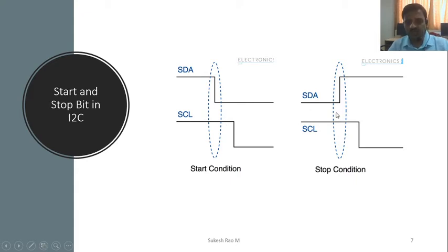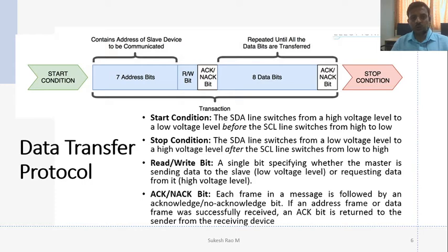Now you have an idea how the start and stop conditions are achieved. The rest is sequencing the data, slicing it as per the number of bits that you want to get. The first thing is to achieve the start and stop conditions. This is very important in I2C, and usually these start and stop conditions are generated by the controller itself. We did not go for generating a start bit and a stop bit by writing separate code for that.